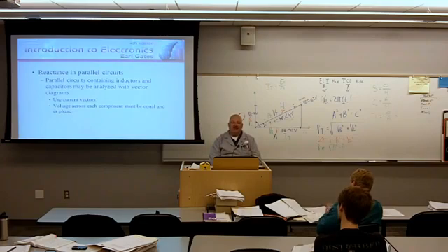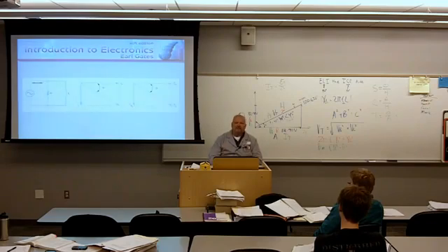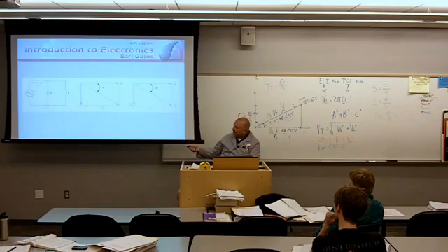So in a parallel circuit, we have to use vector diagrams. Voltage across each component must be equal and in phase. Must be. Whose law is that? Kirchhoff's law, parallel circuit. Voltage is constant across a parallel leg. See, I don't have to draw it. It's already been drawn for me. Here's our parallel circuit. Voltage across the resistor is the exact same voltage across the inductor.